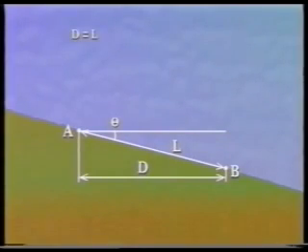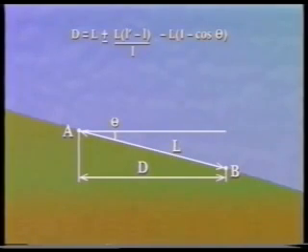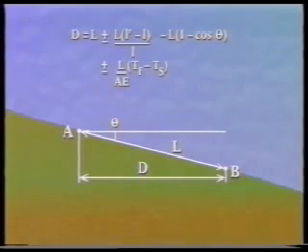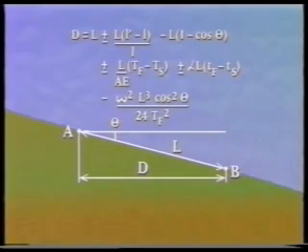D equals L plus or minus the standardization correction, minus the slope correction, plus or minus the tension correction, plus or minus the temperature correction, minus the sag correction.